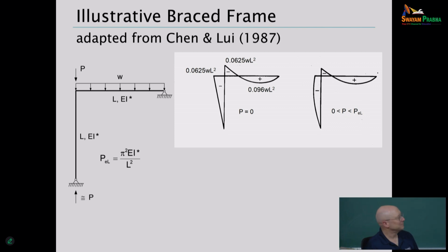Now, depending on the level of load and the slenderness of the members, the maximum moment in the column could be along the length of the column, as you see in this particular sketch. Typically it would always be, but well, actually, that's not true. If the load is small enough, it wouldn't necessarily be maximum within the length. It could still be at the ends.